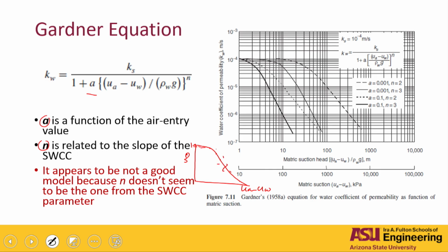You go to Solver. You just put the sum of the square errors to be the minimizing error in there, and then you put any equation you want, right? That the right hand side of the equation minus the left hand side should be 0 or minimized, and basically you find those parameters, right? It's probably a little bit high for our undergraduate students here, but you eventually are going to do that, right?